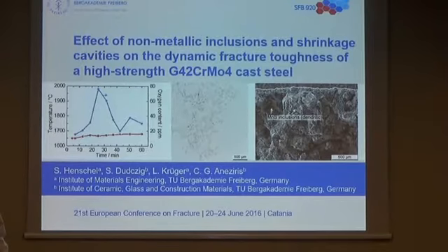So the tensile test showed the following results. Here we have the ultimate tensile strength and the yield strength over the radial position and at different height levels. We see only a slight dependency of the yield strength and the ultimate tensile strength on the radial position, and nearly no effect of the axial position on the yield strength.